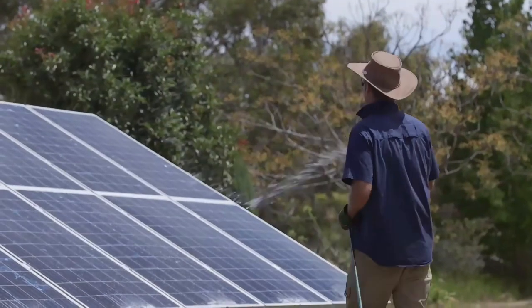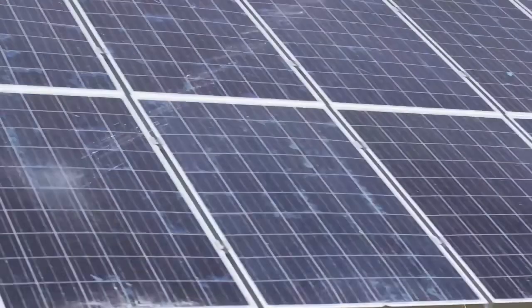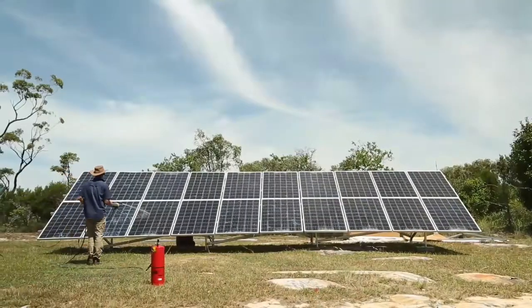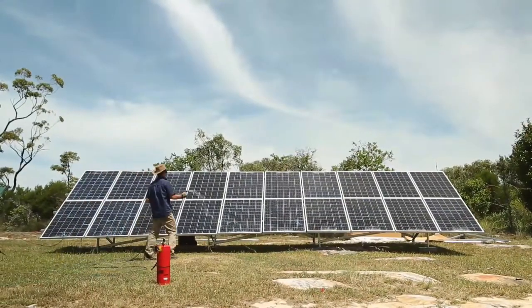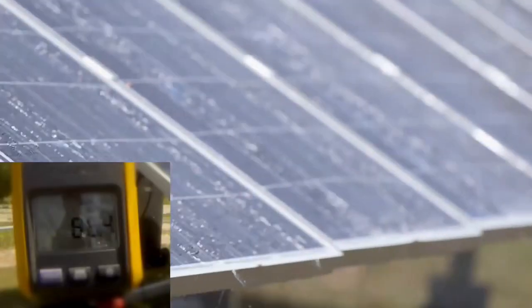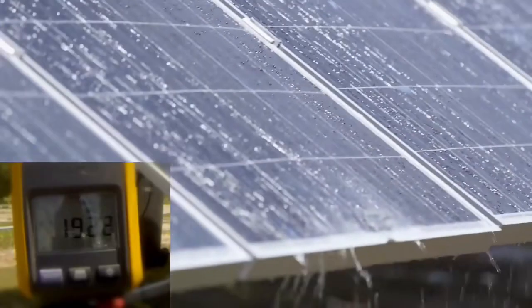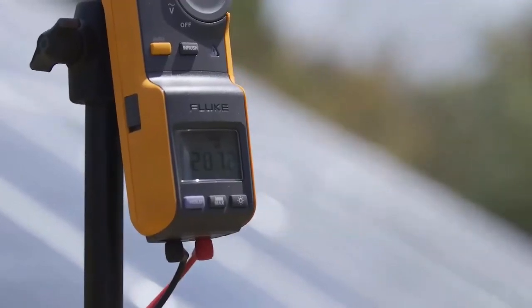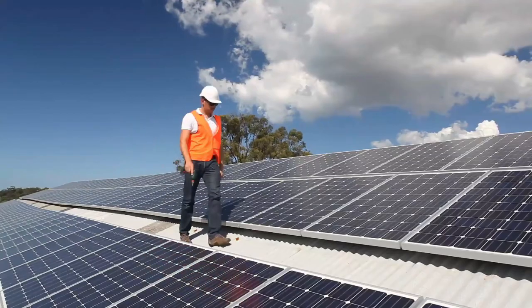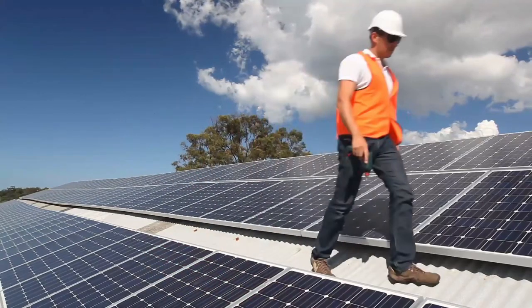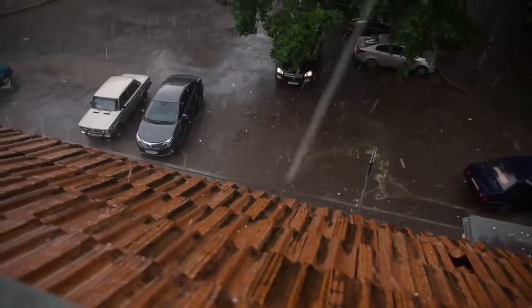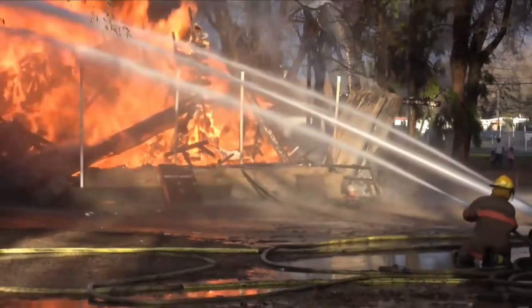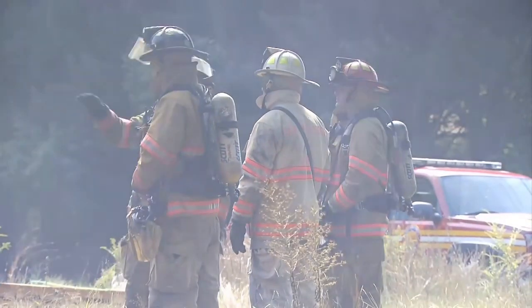To simulate rain associated with a hailstorm or water being applied to an incident involving fire, we then apply water to the damaged array to see if water conductivity affects the amount of electricity that leaks onto the solar panel frame. The impact of water is dramatic. The voltage on the frame immediately jumps from between 12 and 15 volts up to nearly 300 volts, creating a potentially life-threatening risk. If the frame arcs onto metal roofing, this can electrify the roof, guttering, and ladders leaning against the roof. This demonstrates that when responding to incidents involving damaged solar systems, such as clearing stormwater damage in wet conditions or attempting to extinguish fire with water, there is a threat of exposing emergency services personnel to unanticipated risks.